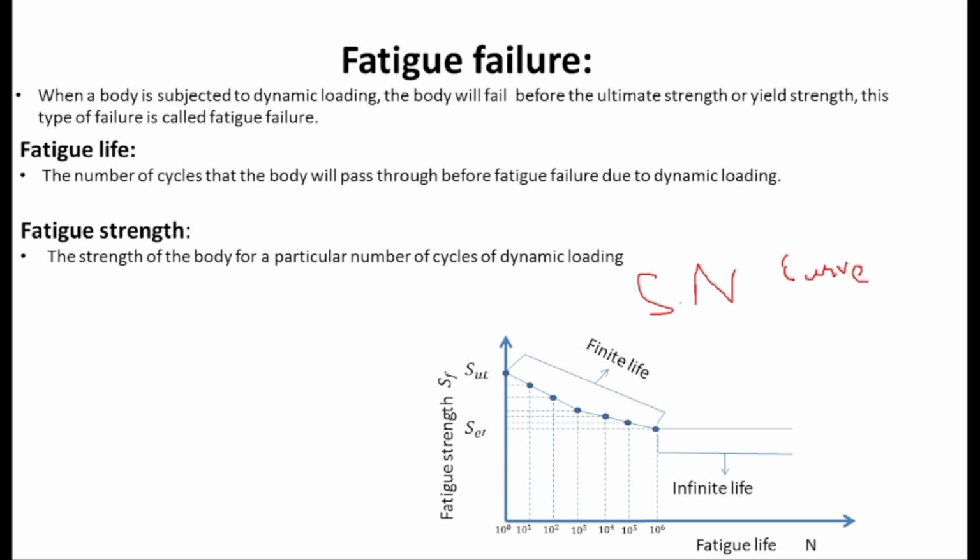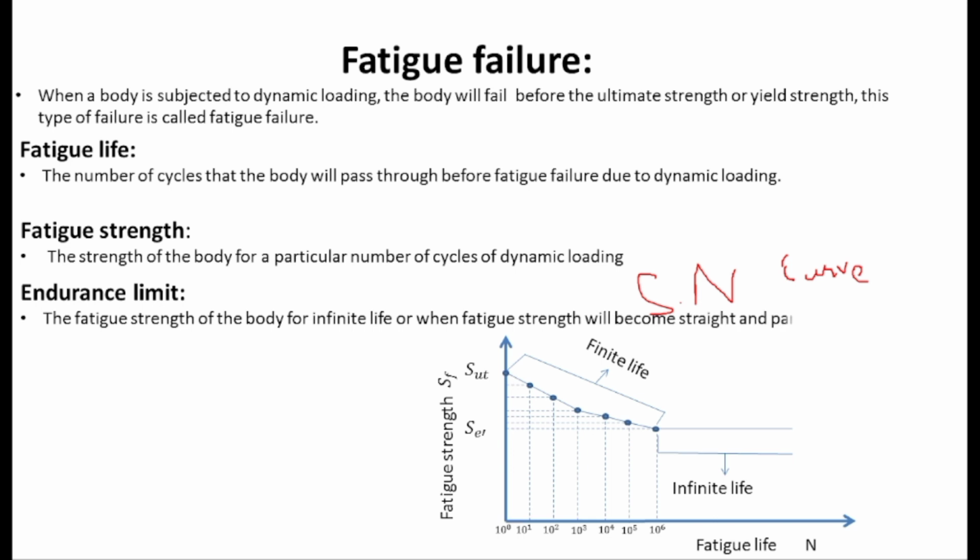Then what is the endurance limit? Endurance limit is the fatigue strength of a body for infinite life, or when the fatigue strength becomes straight and parallel to the horizontal or fatigue life axis. After that, let's discuss stress concentration factor.